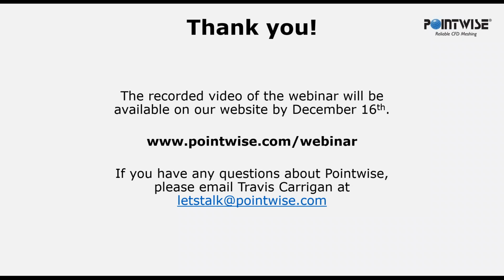All right, are there cases where Delaunay is preferred over an advancing front algorithm other than one failing? In general, from what I've seen in our testing, I actually prefer advancing front and advancing front ortho over Delaunay in most cases. And really advancing front ortho is the one that stands out.